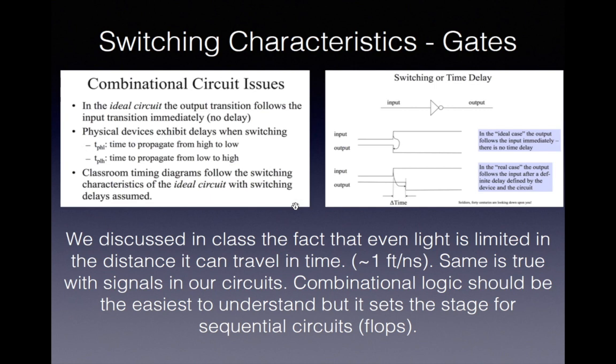But you must keep in mind that in the real world, even as we talk about the fact that light takes time to travel, there will be a delay through all the operations that we use, be it an AND gate, an OR gate, or eventually flip-flops. So you need to be able to explain that yes, when we're modeling, I don't use delays, but I know when I have my circuit built, there will be delays. And it turns out without those delays, we could not build the synchronous digital logic circuits that we utilize.